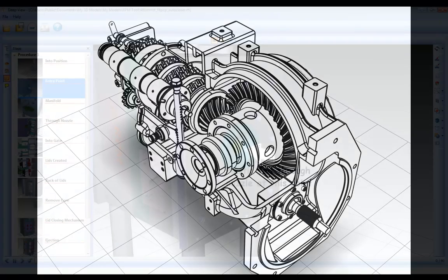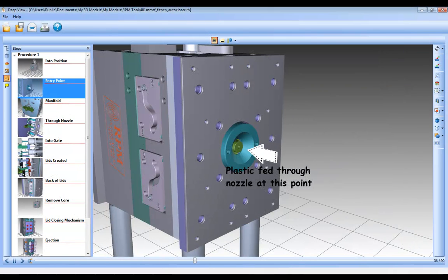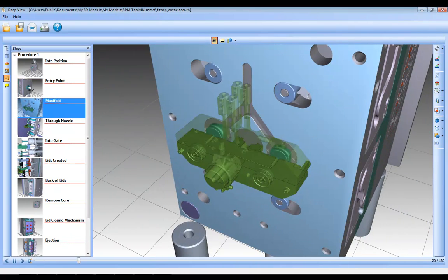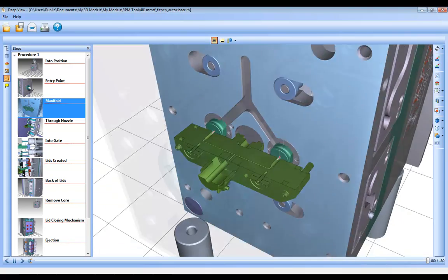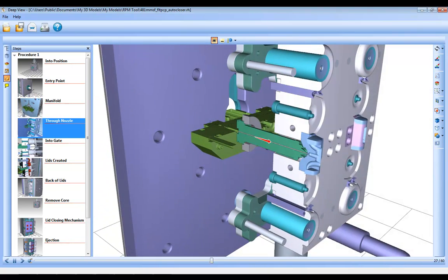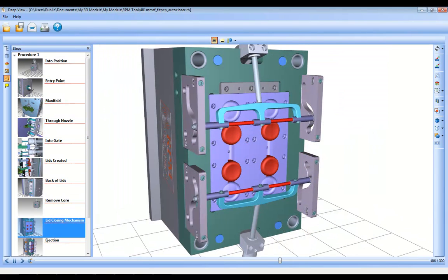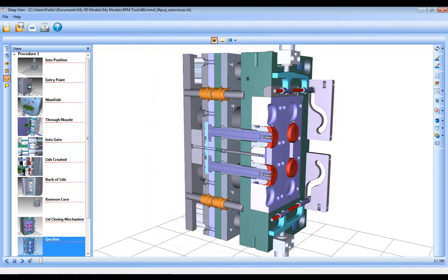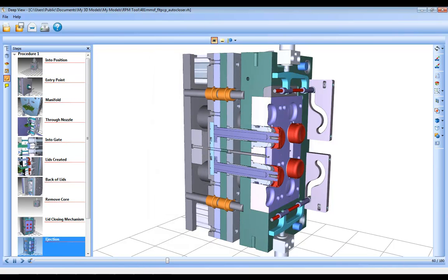And finally, this short section of animation shows firstly the components without sections, and then transitions into having sections cut out of some of the components, to again show internal details. This has been achieved by choosing the option to keep the original parts as well as the negative cuts, and then hiding and showing the appropriate parts during the creation of the various animation steps.